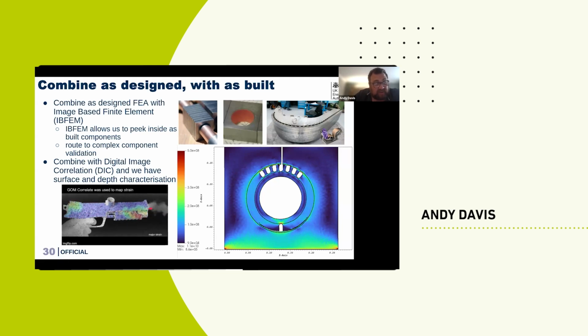So you're seeing the pressure wave, the force of the gas of the ejection and what it's doing to the mechanical structure as this wave bounces back and forth. If you combine this image-based finite element view of the world along with digital image correlation, we have a way of properly validating our mechanical simulations to really show if we understand what's actually going on inside our components. This necessarily, though, brings a bit of a challenge because it means we need to have software which can handle the increased detail that's required.